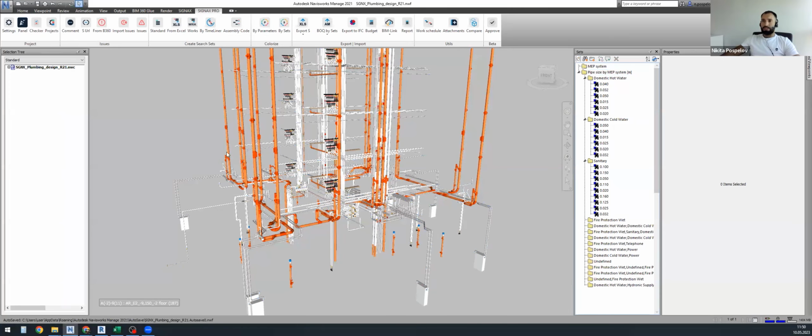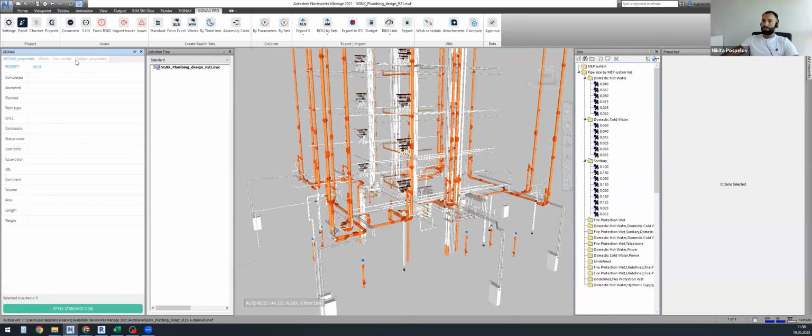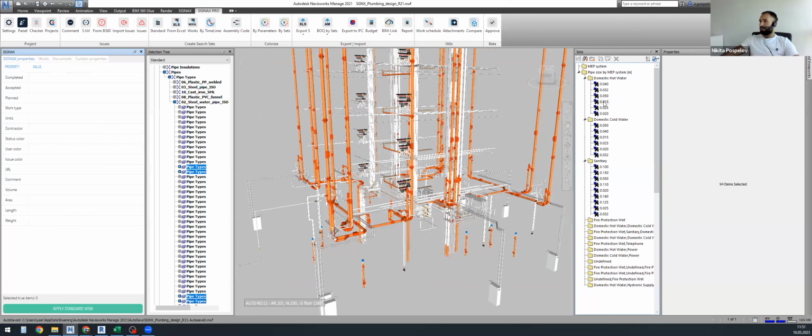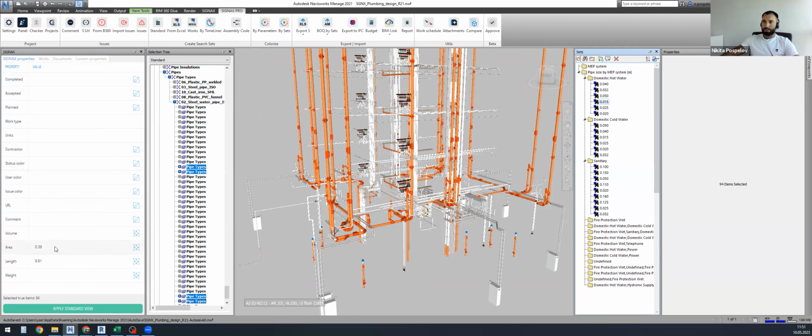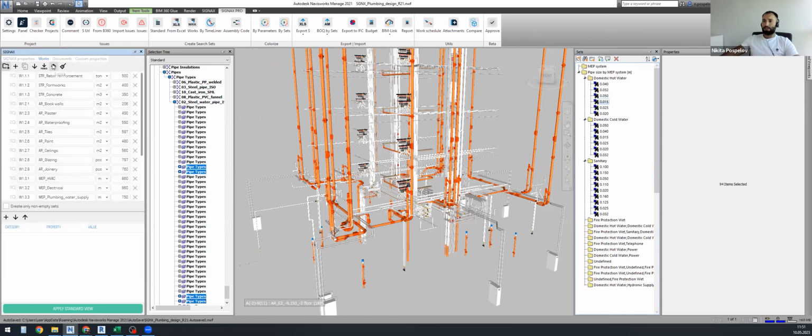As well, we have some abilities and features to add information about the unit costs inside the SIGNAX tools for Navisworks. So we created the SIGNAX tools panel. So anytime you can select one of the search sets created using SIGNAX tools, and we have information inside SIGNAX panel. For example, area, length, that's the sum. And we can go to the work step, and here we can see the work breakdown structure codes, their names, units, and unit costs. So this is used for creating construction BIM models.